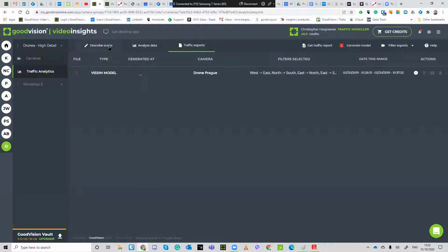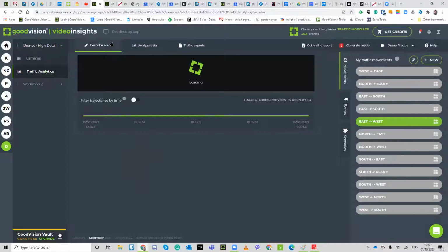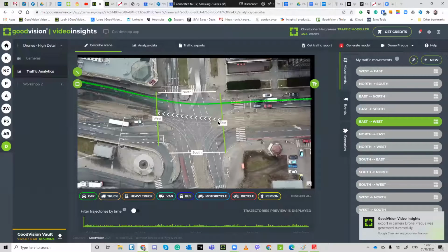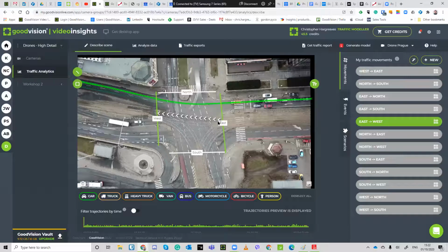And if we go back to the scene now, while that's calculating and generating the model, there's a couple of other things that we're going to look at, and that's generating a couple of the reports. We also want to create the vehicle list report, and that vehicle list report is going to give us the classifications, gap times, entry points and exit points, and also the speeds.